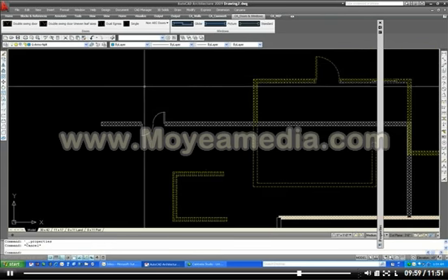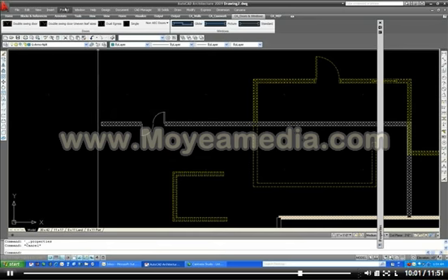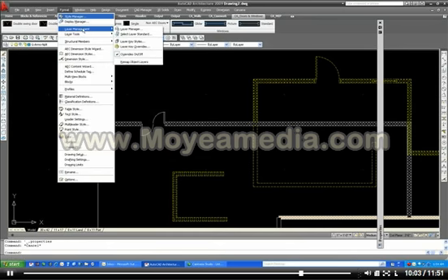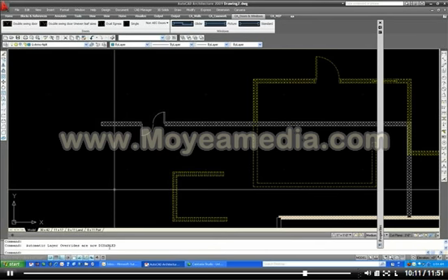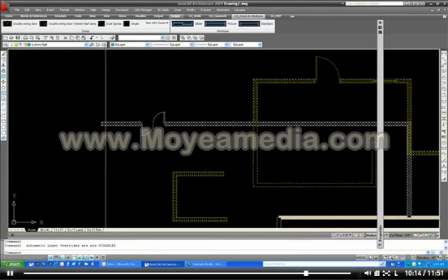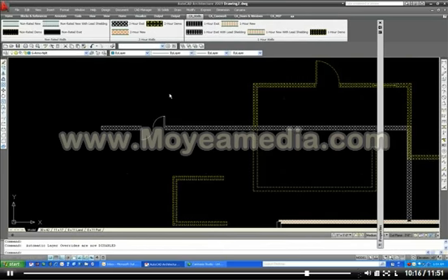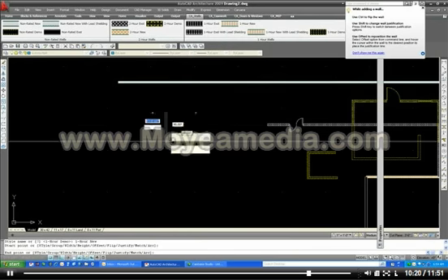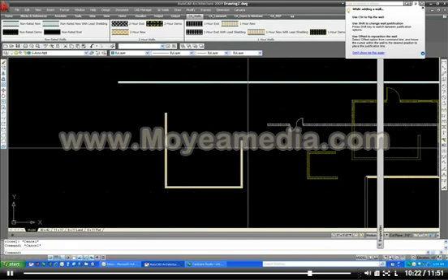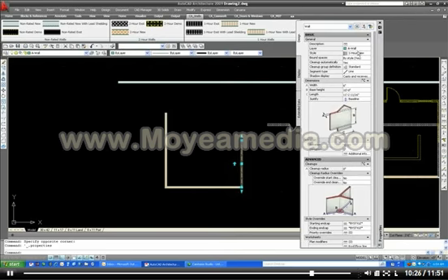And then all you have to do for anything that's new is you can just very easily go over here and select the layer management and just uncheck the overrides. Just turn it off, disable it. So down here at the bottom again, it says disabled. So now you can go back and design any new feature that you want, and it'll come out on the correct layer. So you select this wall, and as you can see, it's on the A-wall layer.